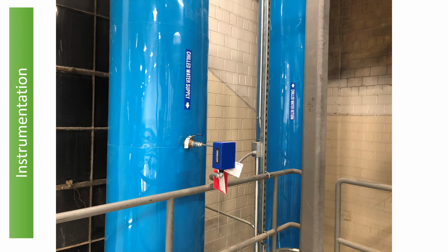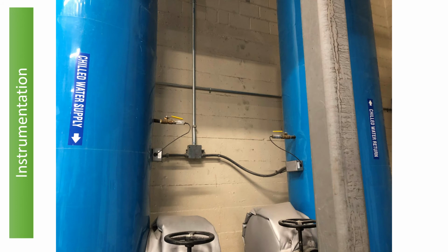And you're like, well, wait, what about those little red dotted lines that went to temperatures? So if we go downstairs, come with me. Now we're in the same pipes, chill water supply, chill water return, and here's our temperature sensors that are both sending their signal back to the building automation system. There's an insertion probe into the water flow of the pipe that reads the temperature.